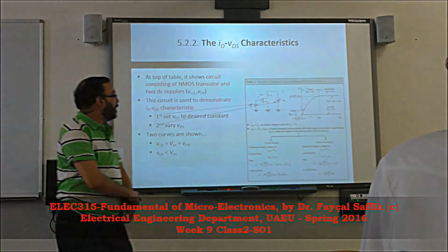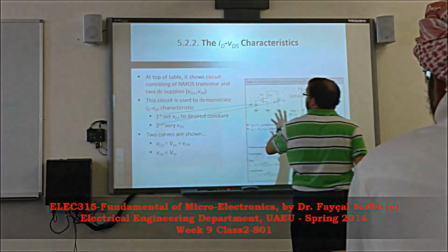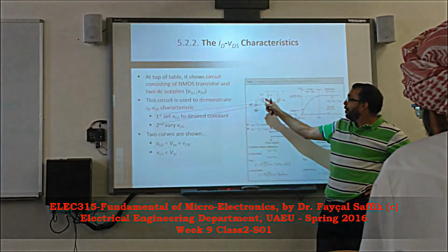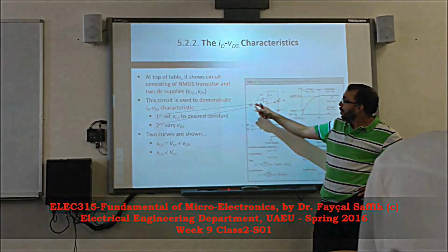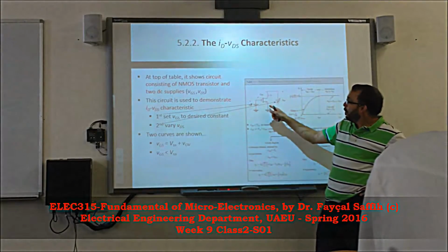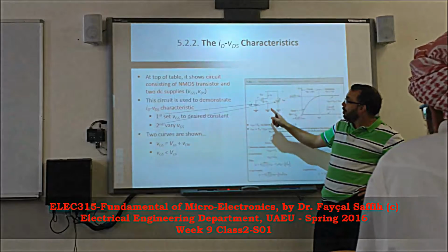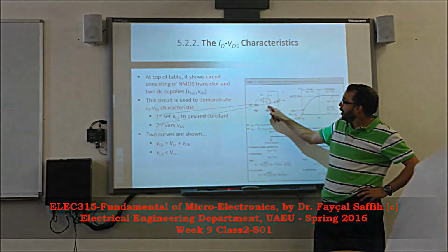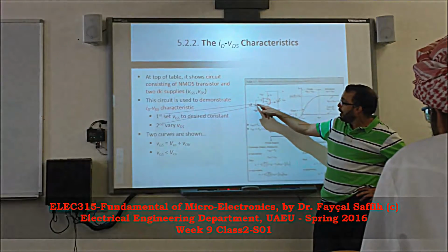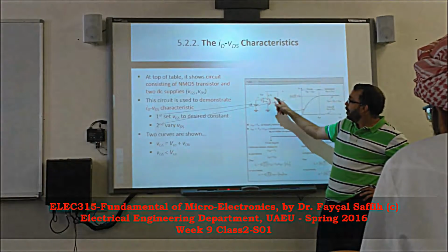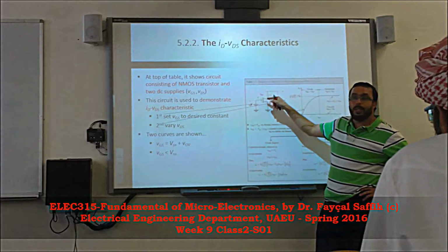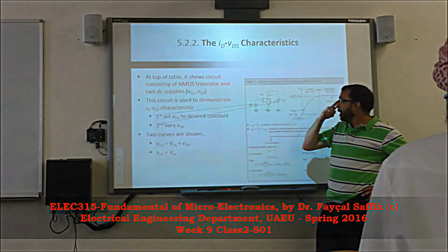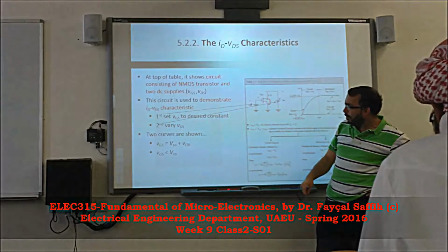So basically, what it shows here is the characteristics, how we do it in real life. First of all, you have to create a channel through VGS. Of course here we are using an NMOS, so the source and the body are connected to each other. As we increase VGS above VT, we have a channel, then VDS will take over and we choose which behavior of the current we get. That's what we did.